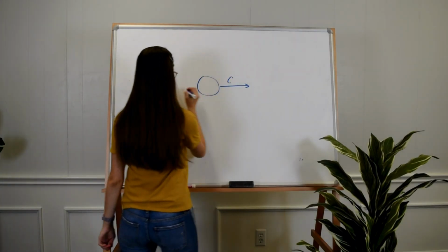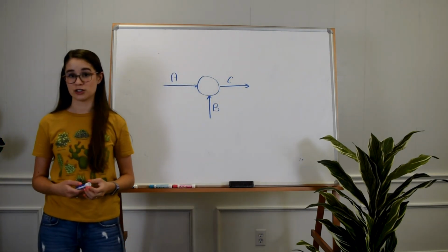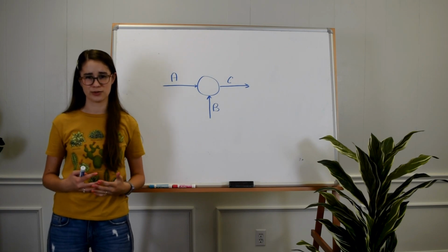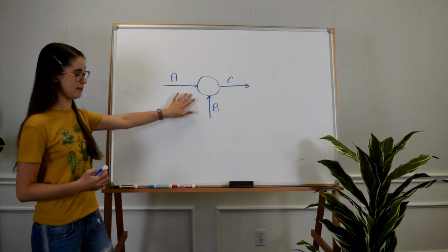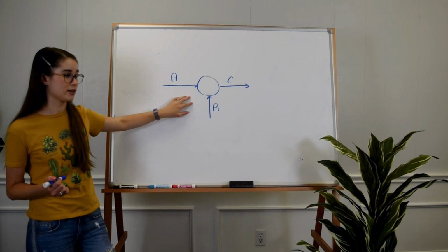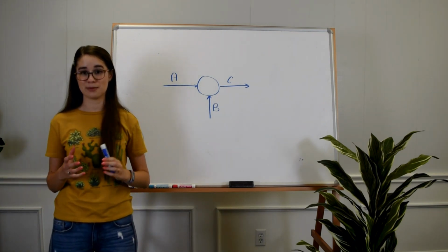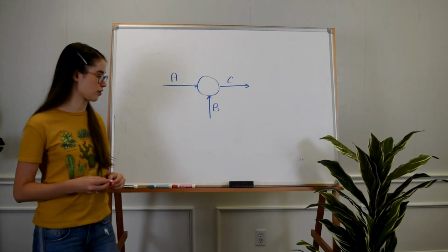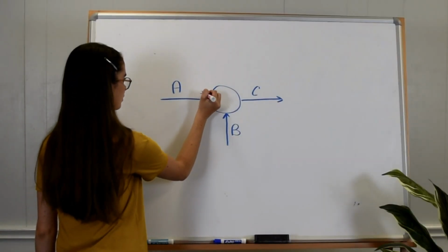So circles take our variables and they add or subtract them. They're used to show feedback in loops, but also can help denote disturbances or sensor noise, anything unexpected that's being added to the system can also be accommodated by a circle. And this picture is not quite complete yet, because the other key thing to know about circles is that we have to include pluses and minuses to denote what we're doing with each variable when we feed them into a circle. So for this case,